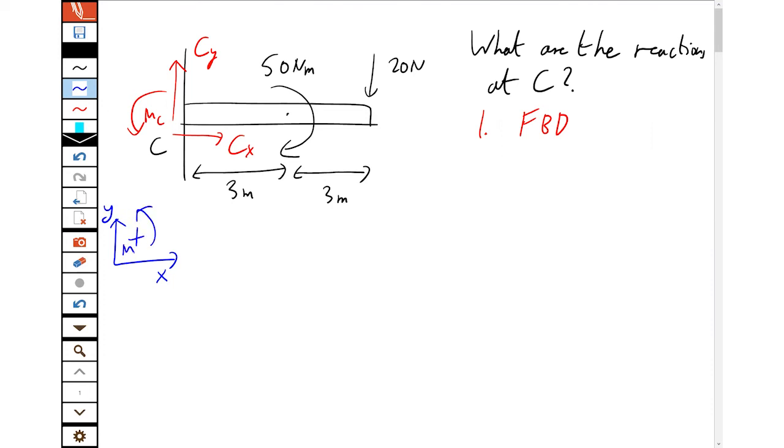And a little tip, we should complete this diagram. They've labeled the point C, but there's two other very interesting points here that haven't been labeled. So we just go ahead and label them ourselves. They're our diagram, after all, and that'll be much easier to deal with once we have some reference points. So next, step 2. We do the sum of the moments around a point is 0. We always choose the point with the most unknowns.